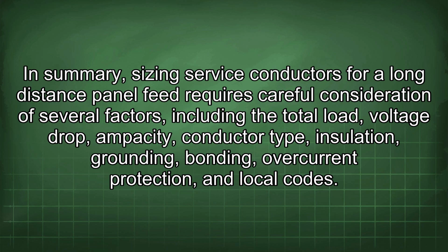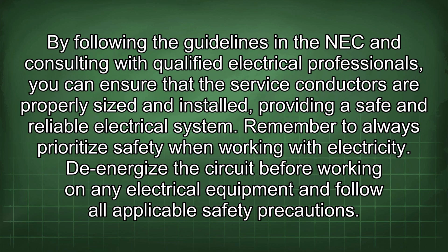In summary, sizing service conductors for a long-distance panel feed requires careful consideration of several factors, including the total load, voltage drop, ampacity, conductor type, insulation, grounding, bonding, overcurrent protection, and local codes. By following the guidelines in the NEC and consulting with qualified electrical professionals, you can ensure that the service conductors are properly sized and installed, providing a safe and reliable electrical system.